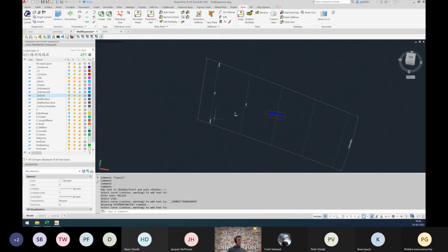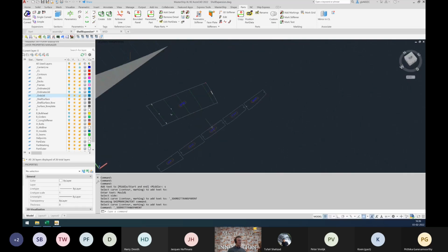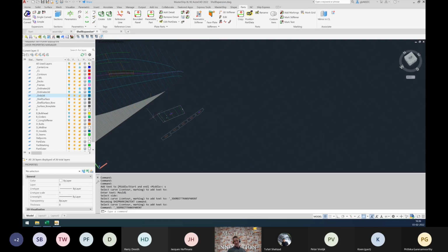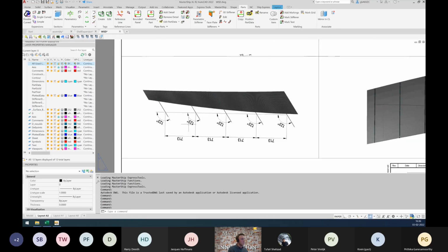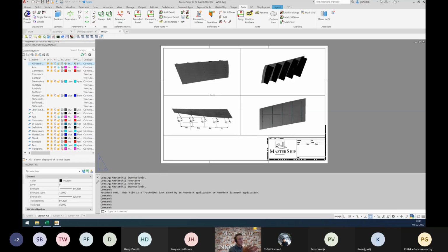So next step would be for this plate to generate cutting code. We are not going to do that in this demo, and same goes for the plate molds. What I did as a final step is that I made a workshop drawing out of it. It looks like this. It's simple and straightforward. Here I put some dimensions on it: the distance between the molds on a horizontal level, and also the angle at which the molds are placed. And that's in fact also the only information that you need.